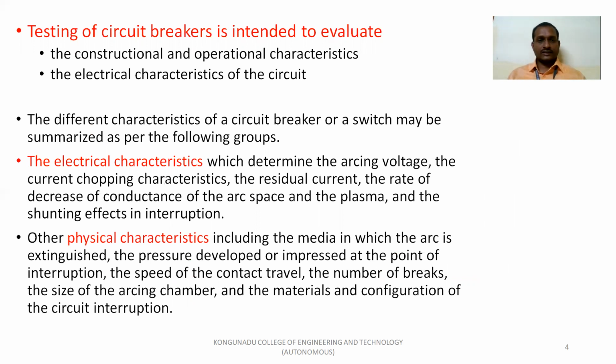The electrical characteristics are used to determine the arcing voltage, the current chopping characteristics, the residual current, the rate of decrease of conductance of the arc space and the plasma, and the shunting effect in interruption. These characteristics will be determined under testing.